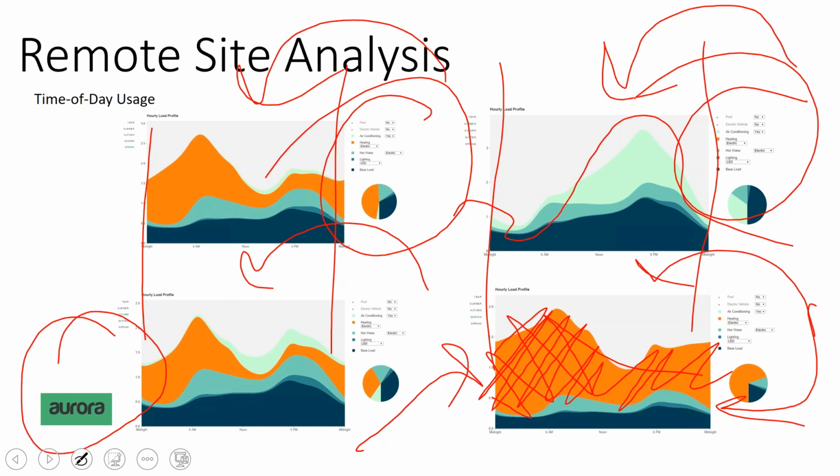The problem that we had is I didn't know what the tip of this curve would be for the client. So I didn't really know what the maximum system output would be. We're used to having 200 amp service panels, but those 200 amp service panels are well oversized. Could we do a 100 amp service panel? Would the client be all right with that?